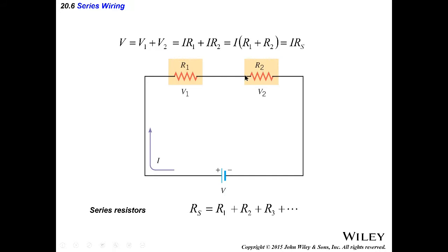It came here and says, uh-oh, my lamp here has no connection from this end to that end because it blew, it melted, it actually just burned out. Then there is no current. If there's no current, all my 99 other bulbs don't light up. You know what I'm saying?